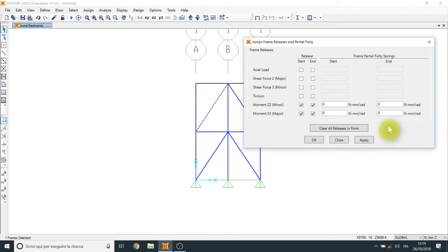In a diagram of bending moment, if you assume the perfect hinges, for example, if you have a distributed load, the diagram starts here from 0. But if you put a value of stiffness, as happens in real life, this is not 0 but is related to the stiffness. This is a function of the stiffness. It can be more clear.